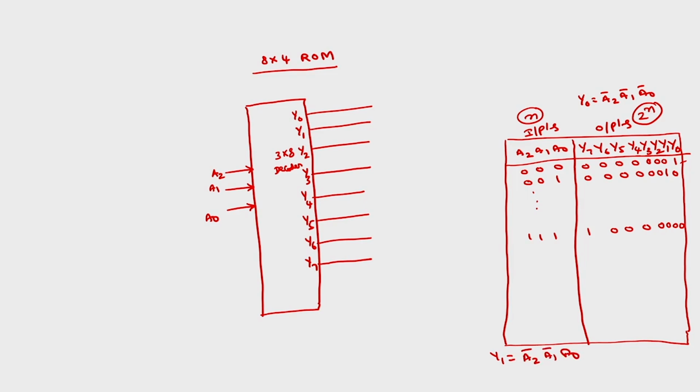Okay. Because all these details are required to interface the memory to the microprocessor. So inside this decoder we will have eight 3-input AND gates. And sometimes we can have some enable signal also. Suppose I want to disable this entire decoder itself; here there is no option, at any time only one of the outputs is selected. So for that I will make one signal such that none of the outputs will be selected, which you can call the enable signal. Okay. That I will discuss later.